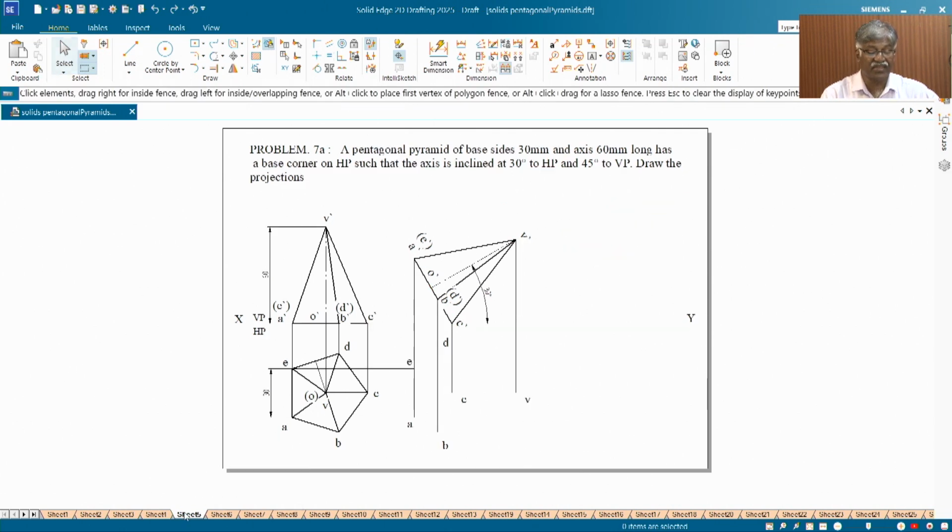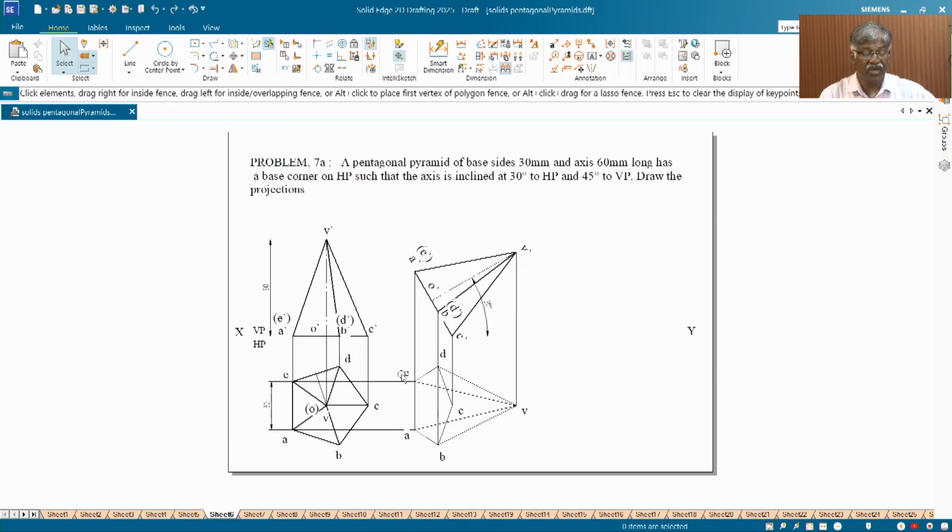Accordingly you do it. Next comes the projections. Unnecessary lines you can avoid. I have taken specific points. Suppose if you take B, that works for E also. If you take A, that works for E, and if you take B, then again it works for D. Unnecessary projection should not be done. Here it's only a single point, X. Next, join all these points.